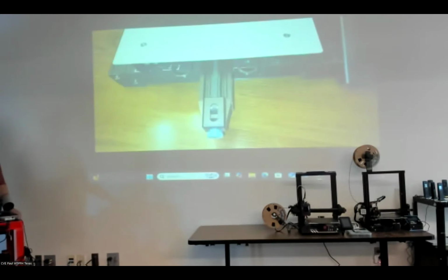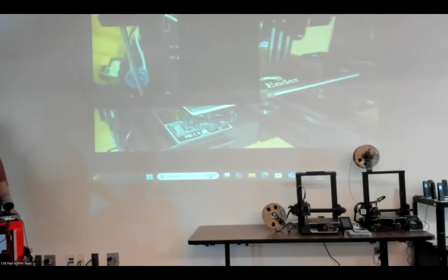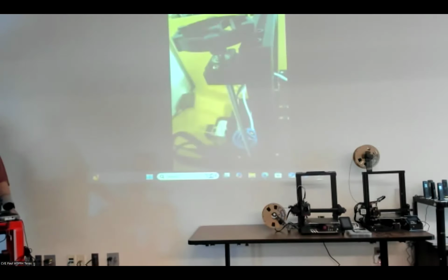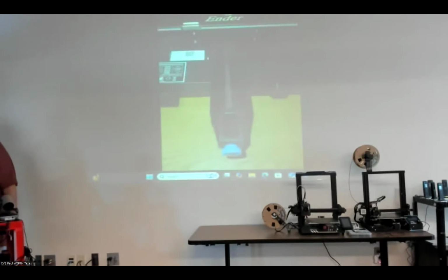So you could have a spool start off really bad and then halfway through the print start cleaning itself up. I've had it go the other way too, where the filament starts off really good and the first 15, 20 layers look pristine, and then it hits one little wet spot and the whole thing falls apart and I come back to spaghetti, like Paul said.